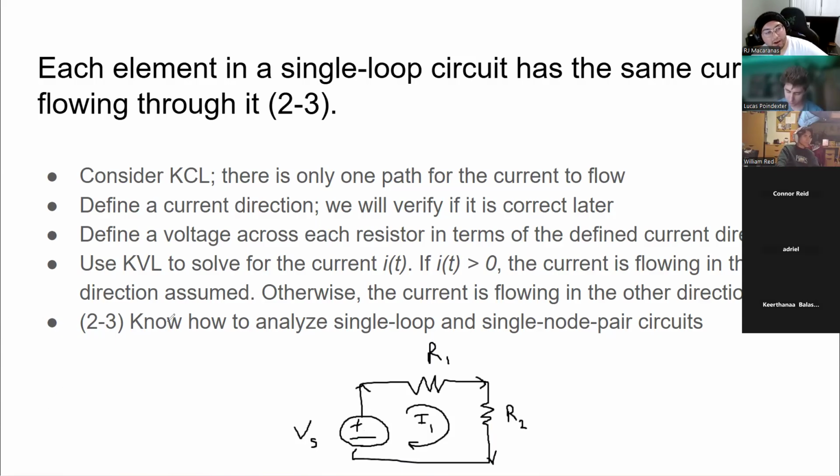All of these elements will have the same current, right? Whenever we look at an element, current in must equal the current out, and that's also true of these nodes. I've got a node here, so the current into that node must equal the current coming out of the node. Once I've gone in, come out through the voltage source, gone into this, I also have to go out through the resistor. What goes in must come out. I've only got one path for current to flow, so current is the same in each of these elements.